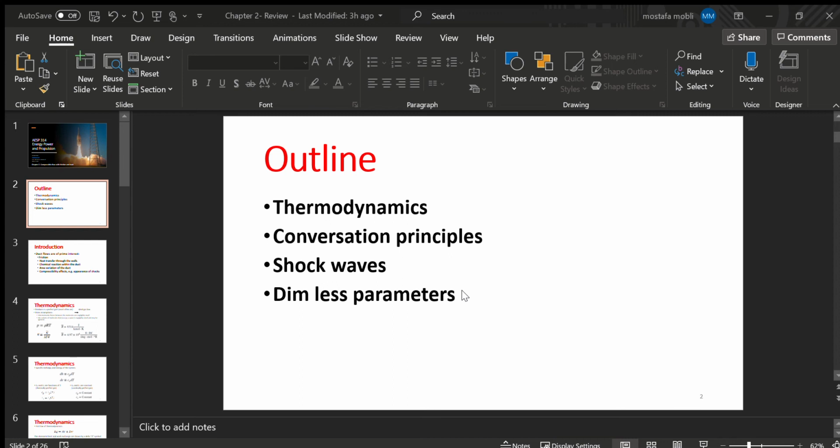Which we can simplify to this for our specific case. We are assuming uniform flow. A lot of assumptions have been made to get from here to here. Okay. So m dot v out minus m dot v in equals the total of forces. Here we are assuming a single inlet, a single outlet, right? We are assuming uniform flow, so we could do the integrations without any problem.